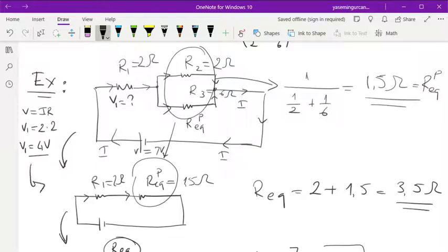So if you look at this picture again here, you have 2 resistors that are in series. And what did we say about series connection? They share voltage, right? V1, and if I call this V2, V1 plus V2 is going to be whatever you apply, which was 7 volt, right? So if we found that V1 is 4 volt, V2 is going to be 3 volt, right? If this is 4 volt, as we found it, V2 is going to be 3 volt because that's whatever the leftover of the applied voltage.